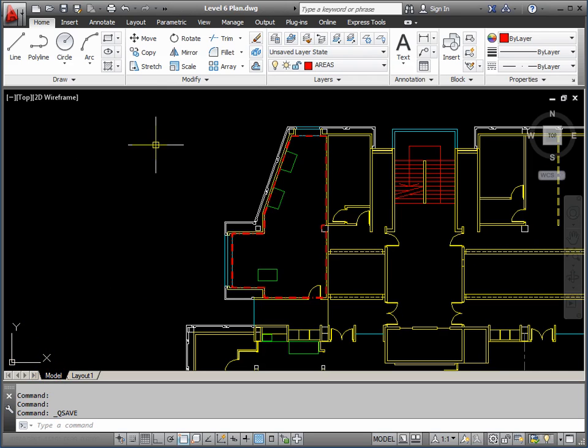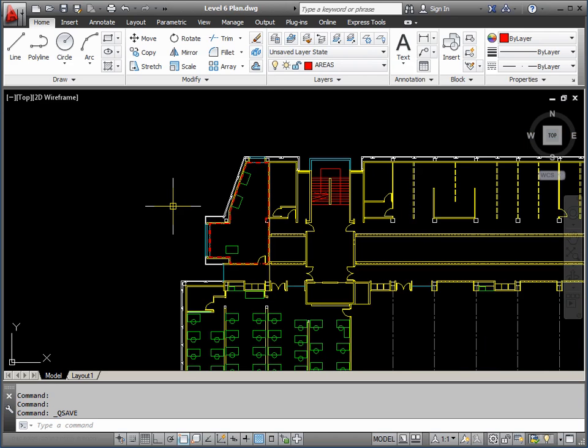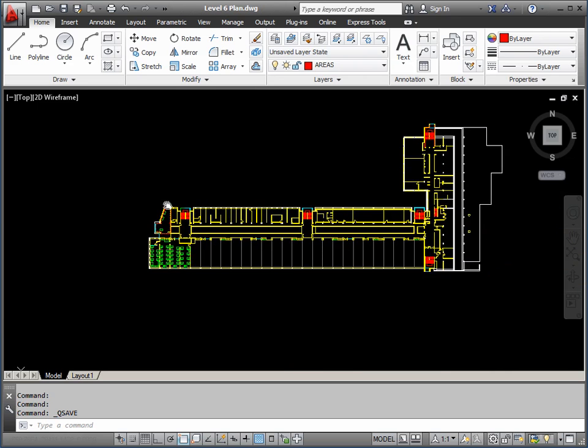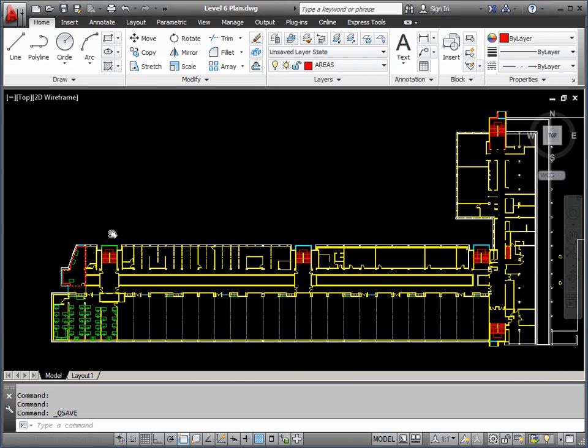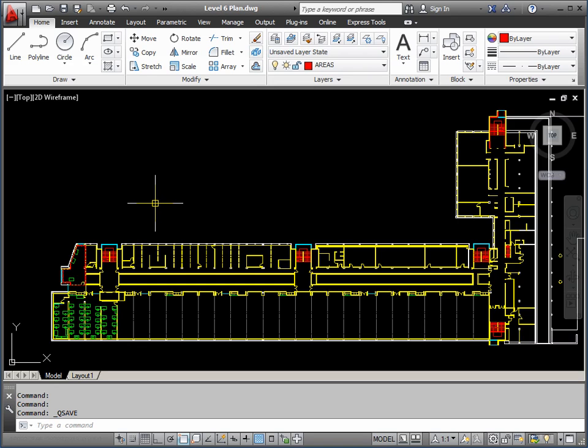Right, I've said already that we have one model space. This is your working area, and there can be all sorts of stuff in model space. You could have the whole building, plans, sections, elevations, details, the whole thing. But when a building gets relatively big, this becomes a bit unwieldy, and we start splitting it up into plans and elevations into separate .dwgs. But within this single floor plan here, there could be all sorts of information required for different people, and therefore we might generate umpteen layouts to deal with different issues, furniture, electrics, etc.